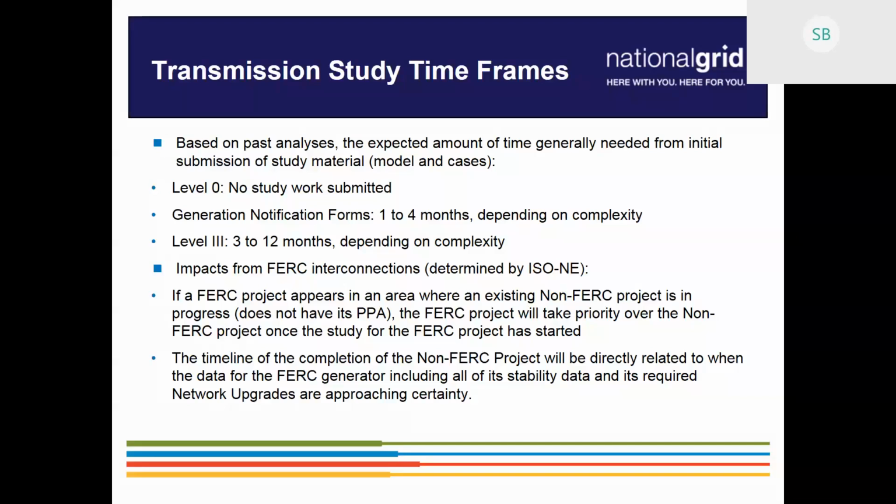What ISO has been calling for is some sort of level mimicking the transfer analysis. They refer to it as a transfer analysis, but it's not the same transfer analysis. There's more detail that ISO performs on the transmission system, I think on an annual basis. This is a more streamlined transfer analysis for the specific projects to demonstrate whether there is an adverse impact based on load flow analysis.